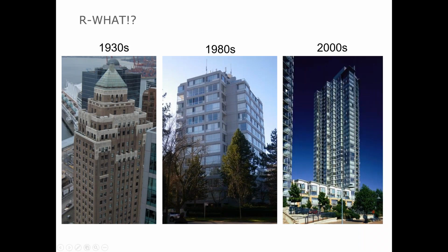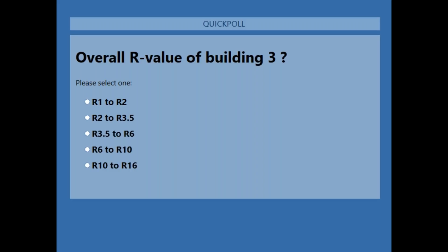And then finally, building number three. So building number three is a more modern building and a lot more glass. It has double glazing in that thermally broken aluminum window wall. It has spandrel bypass in front of all the slabs with some insulation in that bypass area. It has some concrete slabs fully exposed at those small stacks of balconies. Okay, so taking that in its entirety, what do you guess?